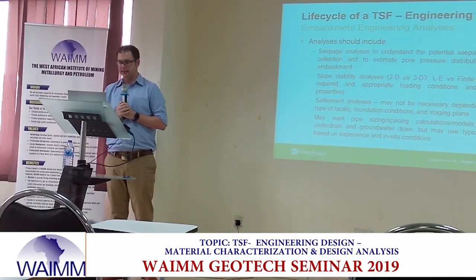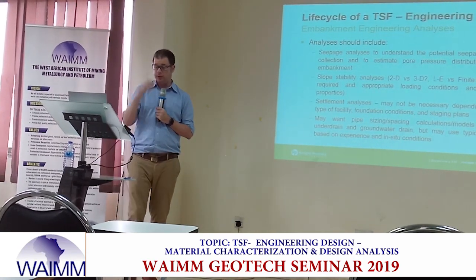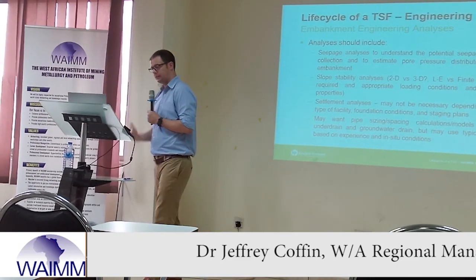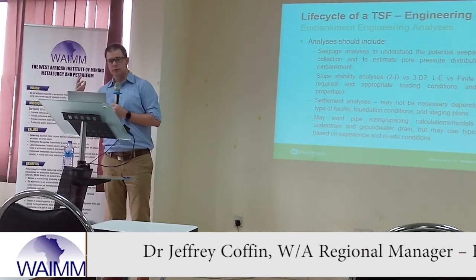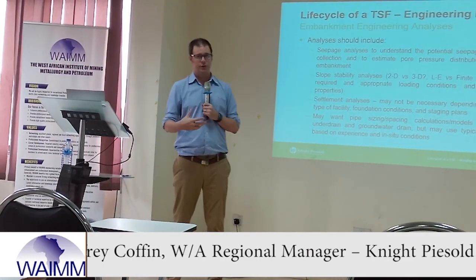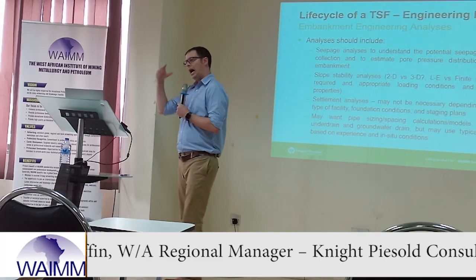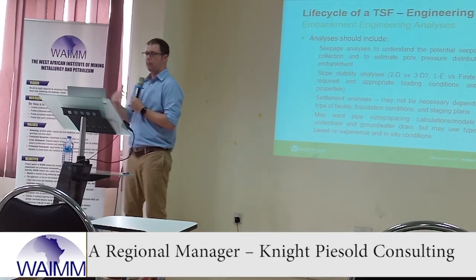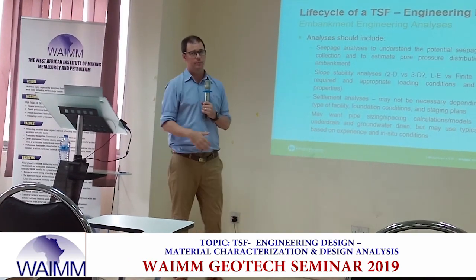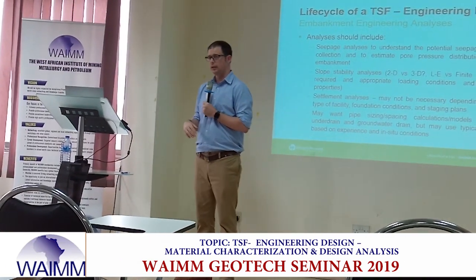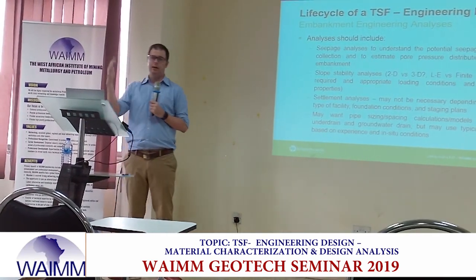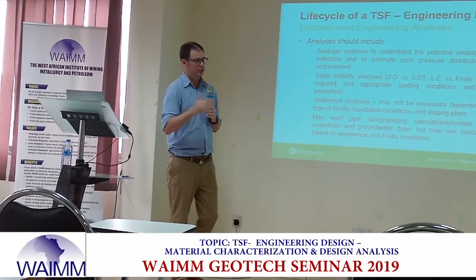So, analyses. What analyses do we need? We talked about this a little bit. We need seepage analyses to understand what type and quantity of water may be passing through our embankments. One, so that we can size our secondary collection system, but two, so we can understand the pore pressures in our dam. We can understand how the facility should behave. As our pore pressures go up, our risk goes up because our factors of safety come down. Right? Our stability reduces. And so we should run our seepage analyses to know what we expect, and then we should be able to modify those to know what happens if we don't get what we expect.